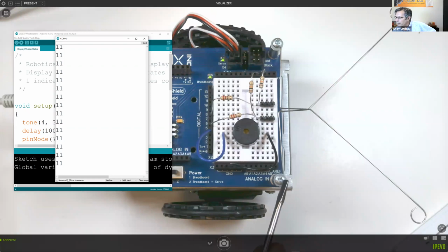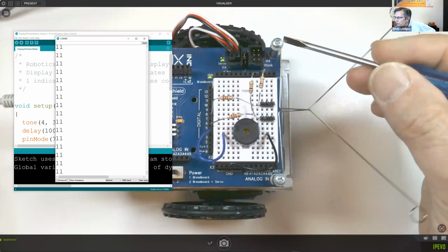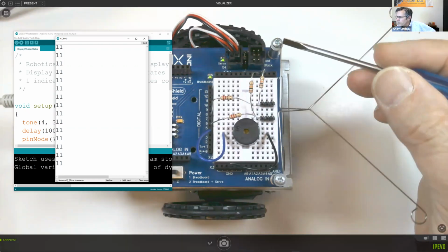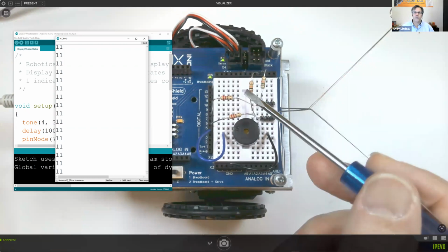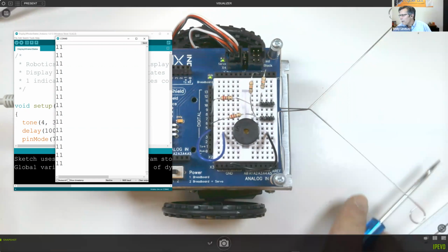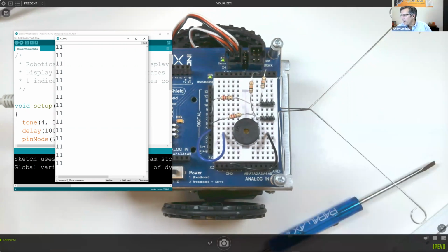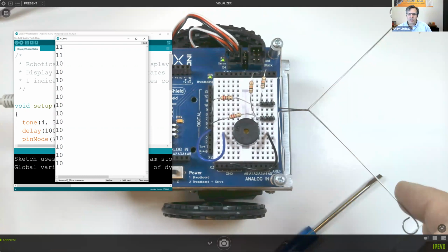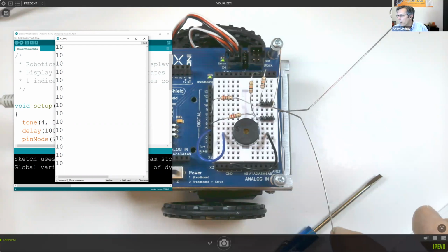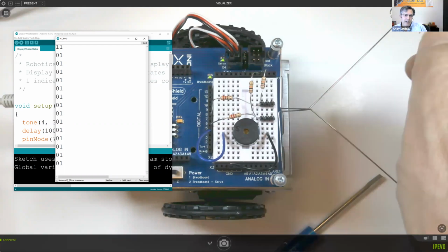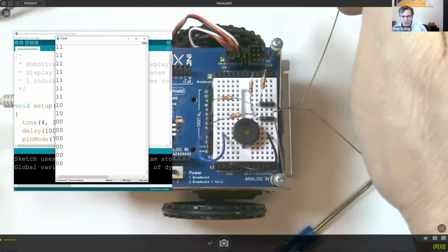And that means that each of these metal posts that's holding a whisker is also grounded. So the voltage here, these resistors here, oh, I'm getting ahead of myself. I have a slide for that. But at any rate, that pin is being pulled up to 5 volts when the whiskers aren't pressed. And when you press the whisker, it shorts those 3-pin headers to ground in a constructive way. And that's how you get the 0 as a result of the contact.